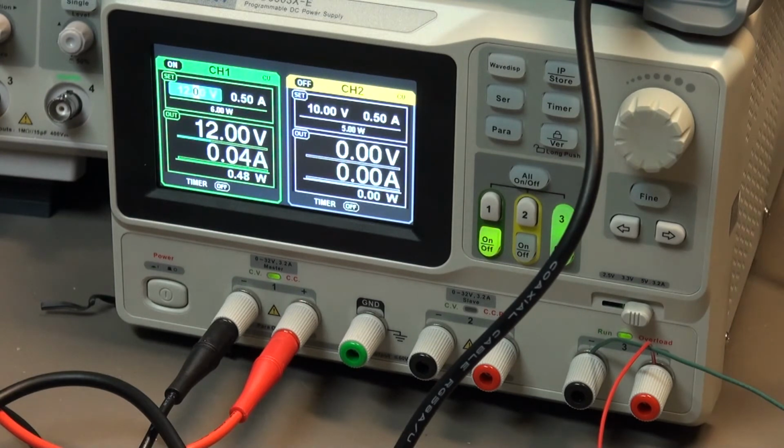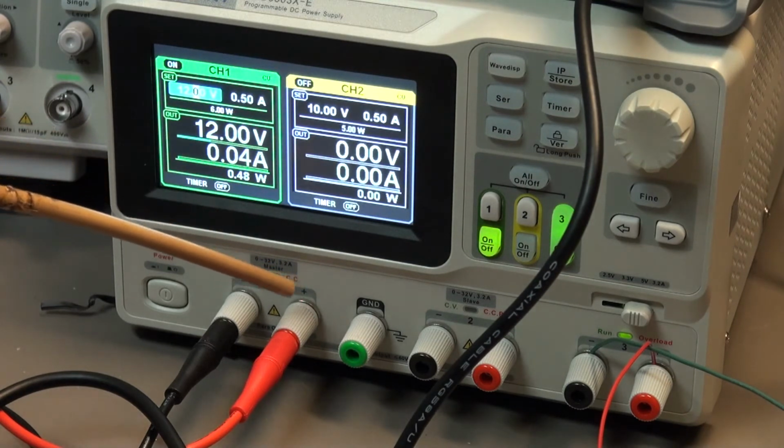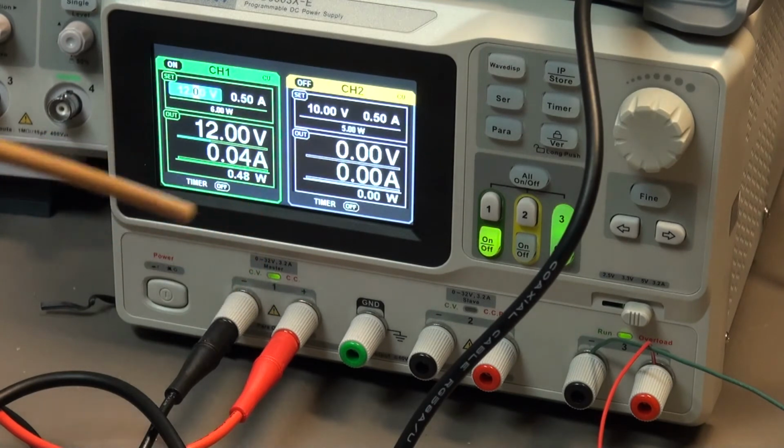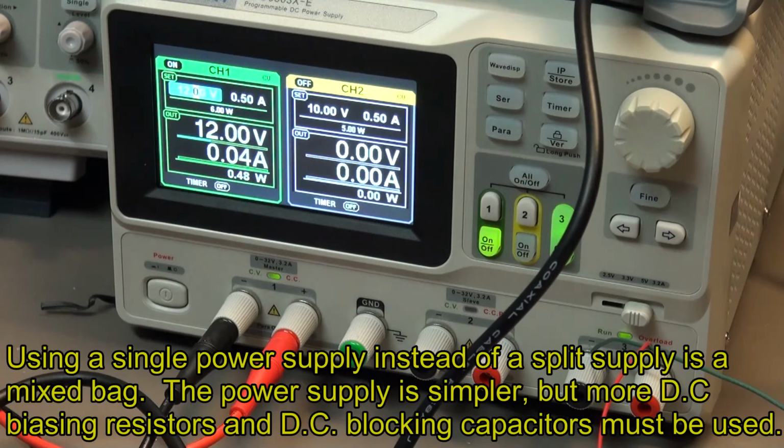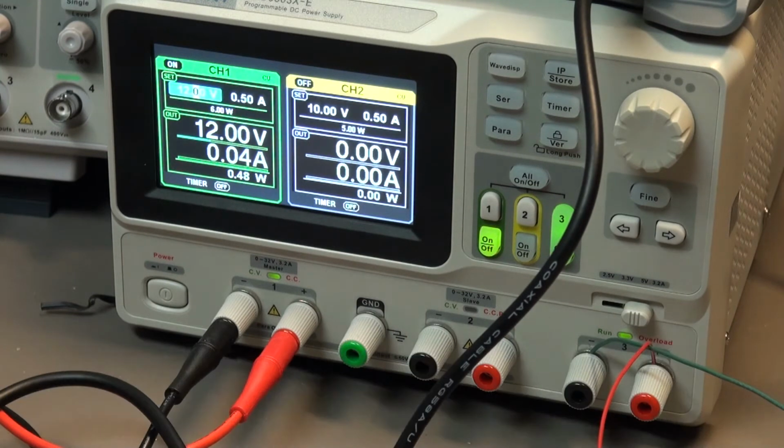Many op-amps are usually powered by split power supplies, but what I am doing is using a single supply of 12 volts and ground, negative. And the reason for that is my goal eventually is to use this gadget either with a 9-volt battery or maybe a 9-volt and 2 AA's for a total of 12 volts out in the field. So it's not very convenient to use split power supply. And as I go along, I will be describing the various circuits and how I bias the op-amps and so on for single supply operation.